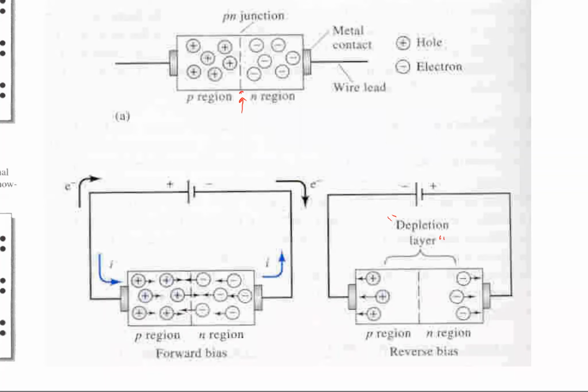Right here at the interface, okay, some of those electrons which are present in my N-type material may migrate just a little bit, we're talking about micrometer dimensions here, into the P-type material and start filling in holes. Now, if those electrons migrate to the P material to fill in holes, think about what's going on right at that interface. The excess electrons have been removed and the holes which were present have been filled in. So if we make one of these junctions, if this process occurs right there at that interface, it's going to pretty quickly become non-conductive.